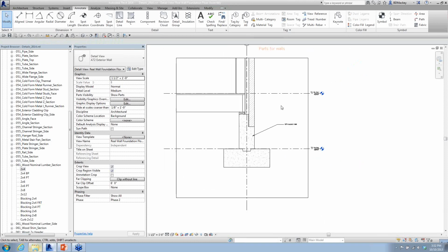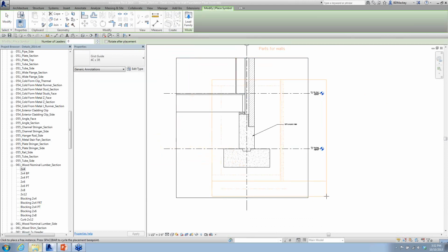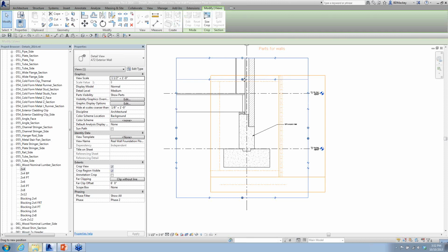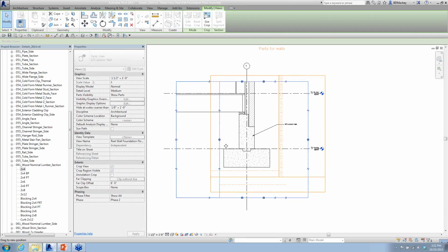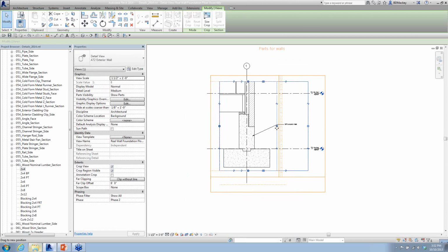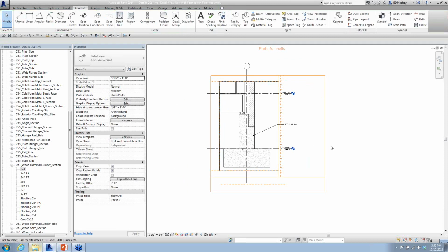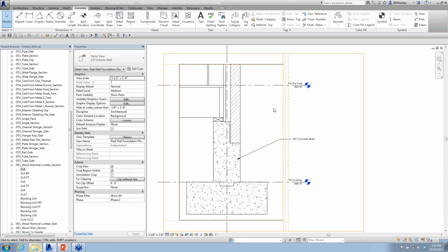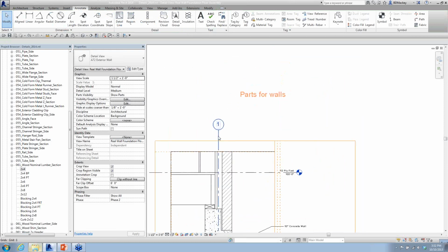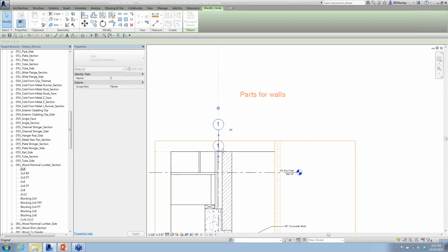And the other thing that I always like to show, even if I'm working over the 3D model, is I'm still going to use my grid guide family. So I need to detail this. I'm going to come through here and place this nice little grid guide family over the model, because now I understand that model. I need to take the crop region and pull it down so I'm not seeing so much of that model. Take this crop region and pull it in. So even if I'm detailing over the 3D model, I'm going to be pulling in my crop region to get outside of the object so I can be where I need to be. So that guide grid family, I love it. I use it even if I'm over the 3D model.